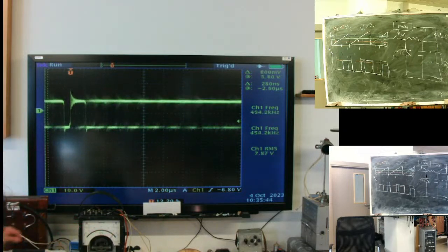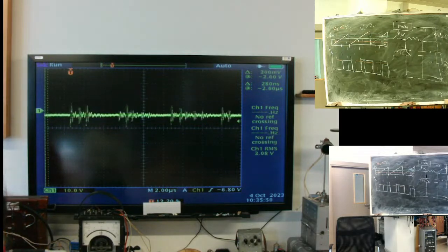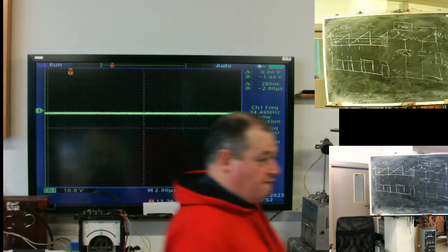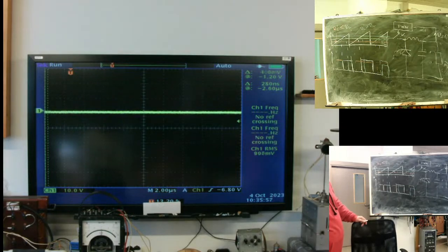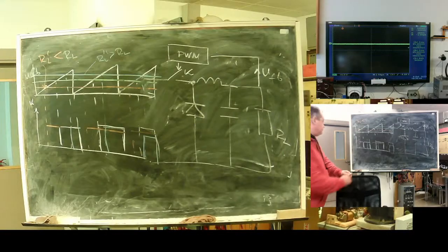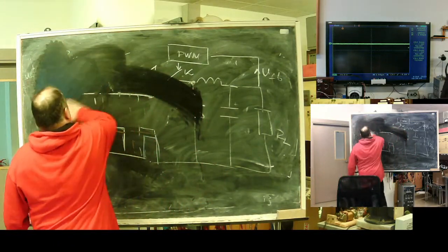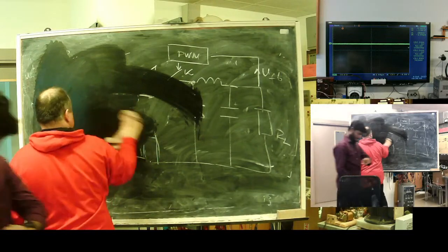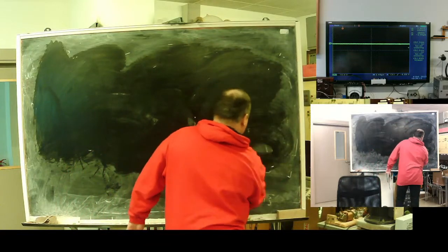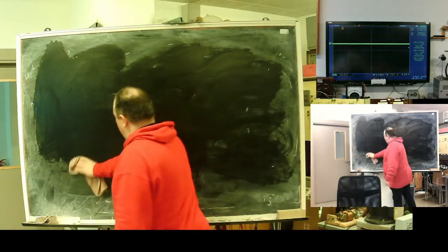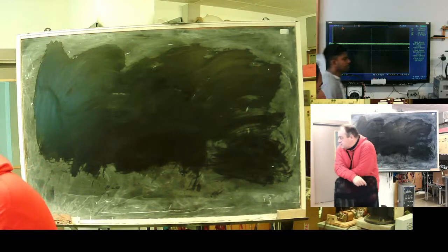So what we see here is an object, let's say, a constant volt-ampere, constant power load. Such a thing is very typical of city transport, like trams, trolleybuses, commuter trains, and so on. Metro trains are powered from 600 or 3000 volt DC networks.